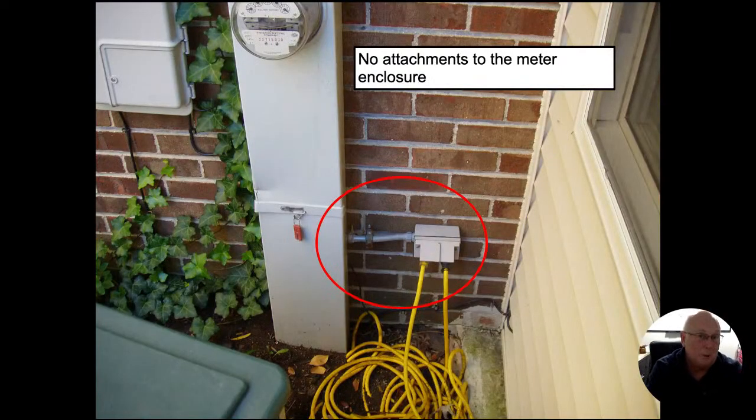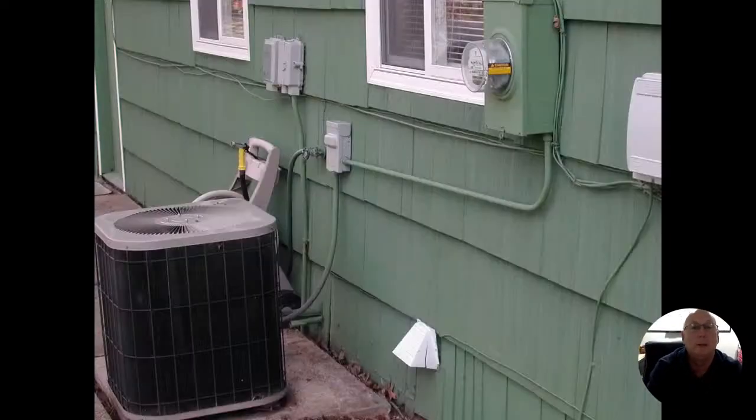Meter panels are not supposed to have anything coming off of them. All right, so if we do see an outlet or something in here, we don't know if it's before the meter or after the meter, but either way, we're not supposed to be using the meter panel as a junction box. And so we can't run wires through it. So we shouldn't see any taps coming off of it either. This one I just thought was pretty cool. They could have advertised that free air conditioning was being given.